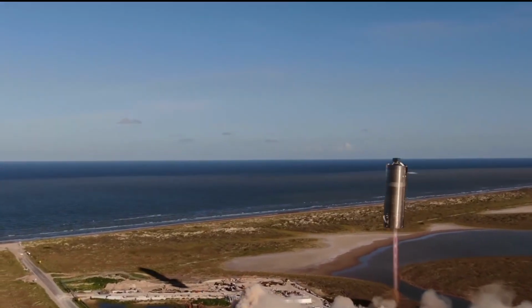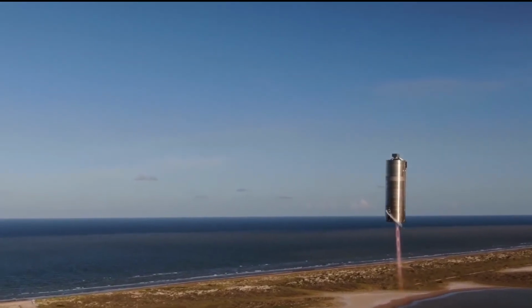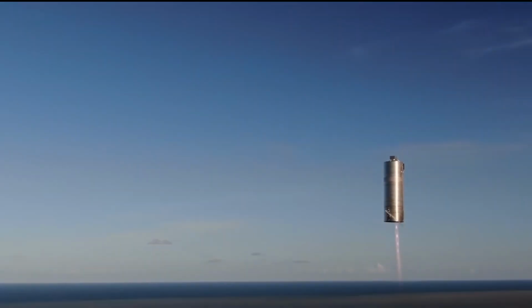just possible on vehicles with just one Raptor, and since that won't happen ever again, the engines are restricted to gimbaling towards the outside of the vehicle and therefore away from the other engines. If they were to gimbal towards the center of the vehicle, they could damage themselves, so they won't do that. All in all, the gimbaling system is probably as simple as it can get. You could even try to rebuild such a system with Lego bricks if you wanted to.